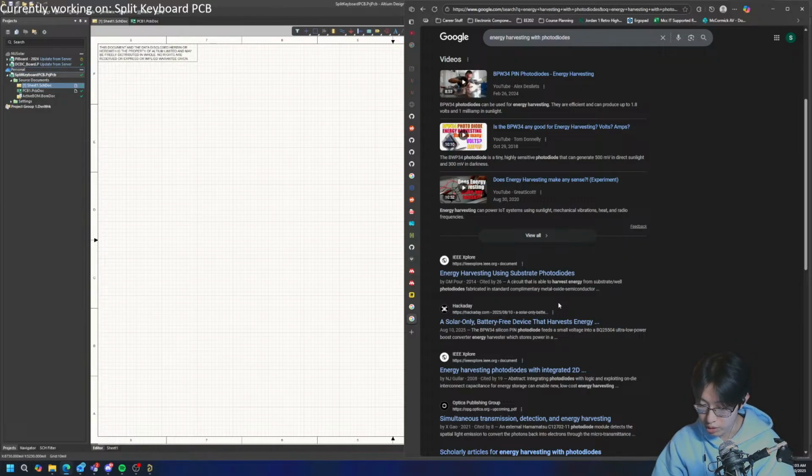If you had a microcontroller connected to each one of the battery's terminals, when the car is not on, you could still get the voltage of the battery by harvesting energy through the photodiode. And then as soon as it gets enough energy to actually transmit something, it just wirelessly sends a packet to like a central controller that tells that controller what the voltage of the battery is. So no matter if the battery is actually on or off, you know whether or not it's in a state to be turned on.